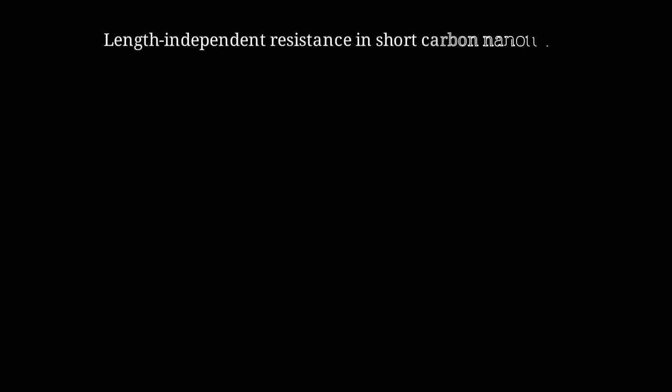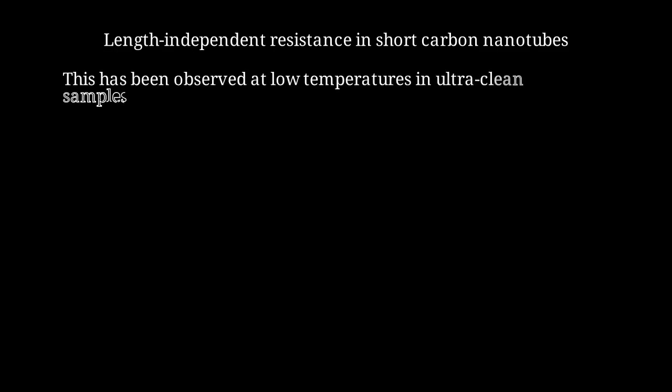Another striking example is carbon nanotubes. When carbon nanotubes are shorter than the mean free path, their resistance is independent of length, confirming ballistic transport. These effects are typically observed at low temperatures, often below 10 Kelvin, in ultra-clean samples where phonon scattering and impurity scattering are suppressed.